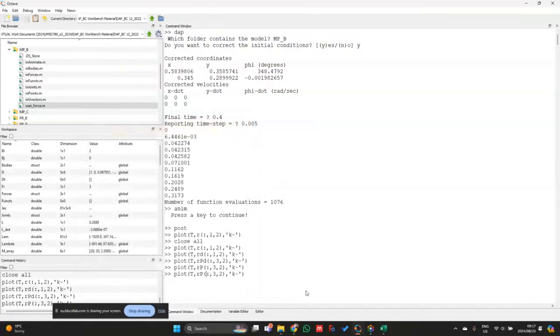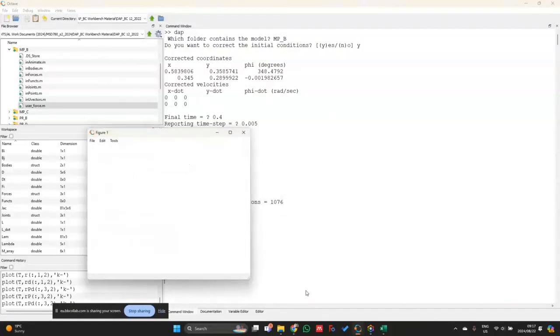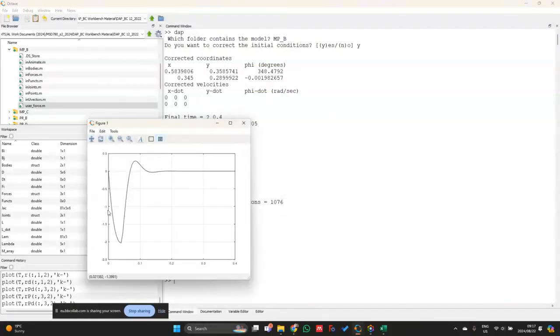And lastly, we can also plot RPD. And we once again have this velocity curve over here. So an initial downward velocity, since the tire is moving down, and then once it reaches ground, then it's going to have some sort of a bouncing effect over here, and that's where we see the upward velocity, a little bit downward, and then once again the velocity is 0, where it then reached equilibrium, or where the tire is then stationary in the Y direction.